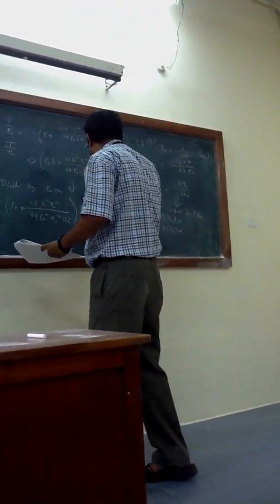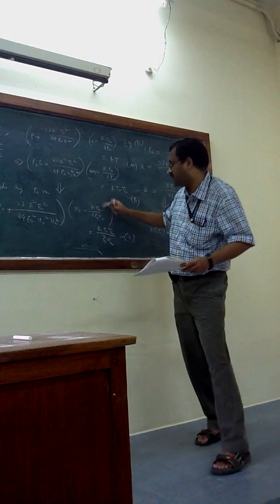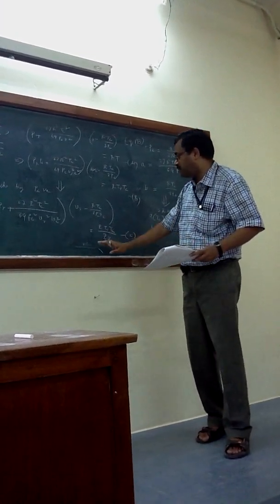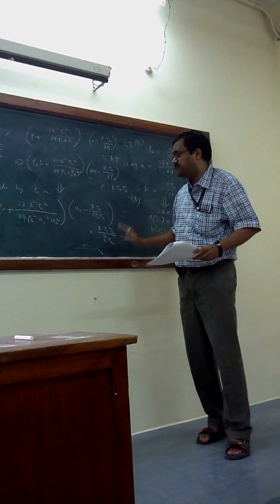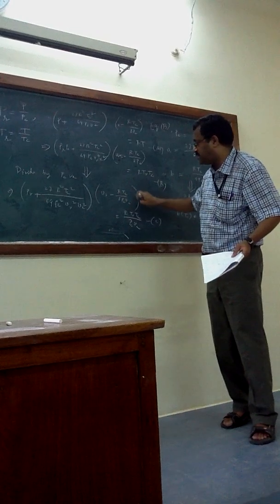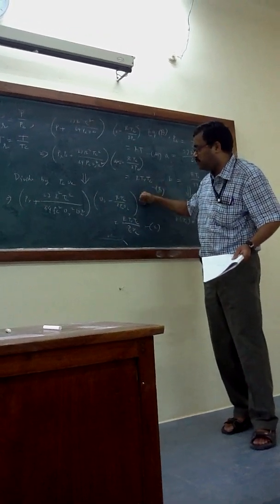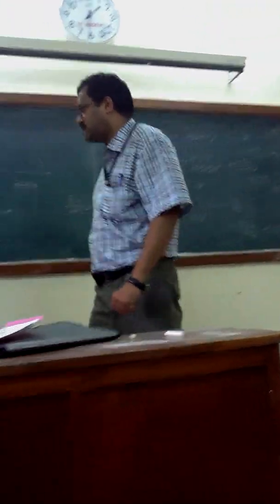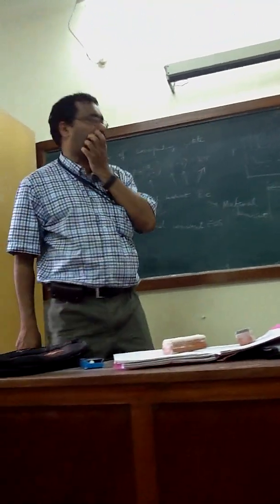That is important for this term. Because if you can calculate, we can take the reciprocal and get the answer. The final equation of state should not have any TC, PC, BC. Only PR, VR, TR are allowed. If I can replace with that, even ZC also, if you do, the answer is wrong, because I should not have any material properties. Otherwise the law of corresponding states has no sense.